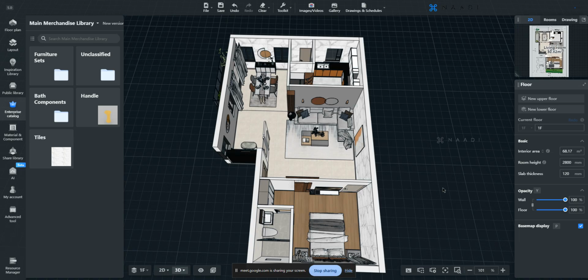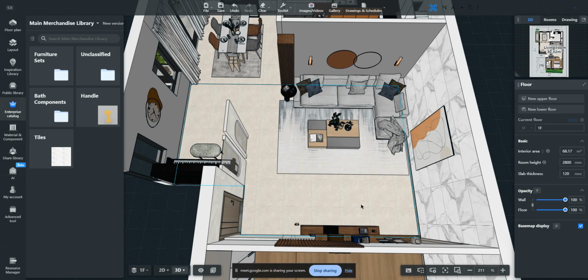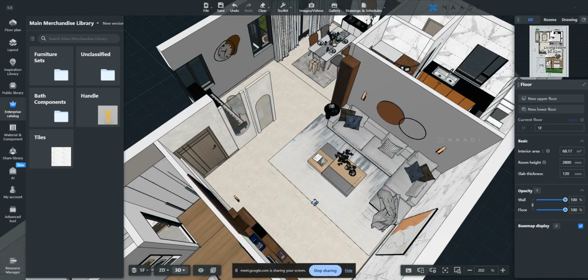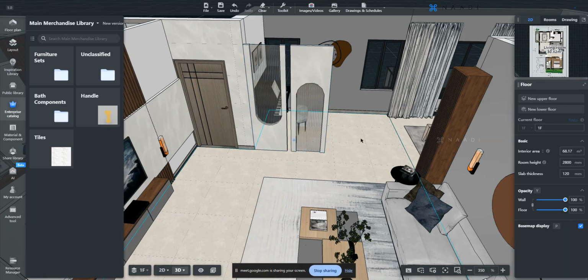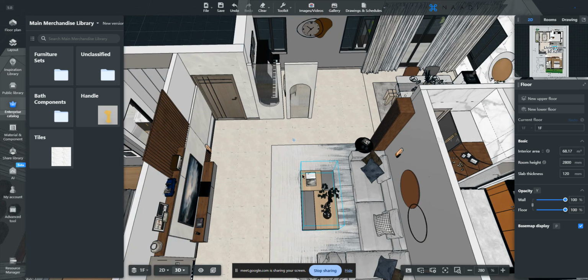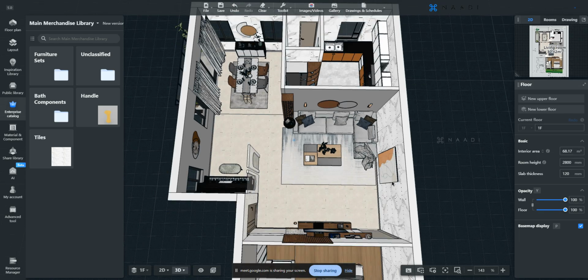Modeled in the sense of your model placements, your furniture placements, your finish applications for your surfaces, and your wall decors. If you want your propping to be there in your 2Ds, make sure that is also modeled. And most importantly, your wall panels, false ceilings, and if you're having cabinets, make sure those are also modeled. Once all those components are modeled, you should be able to generate your construction drawing.